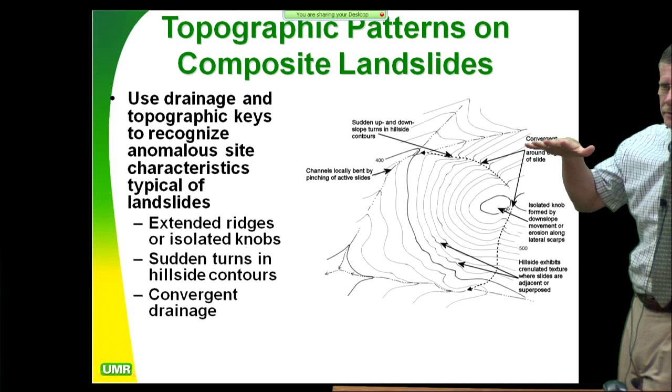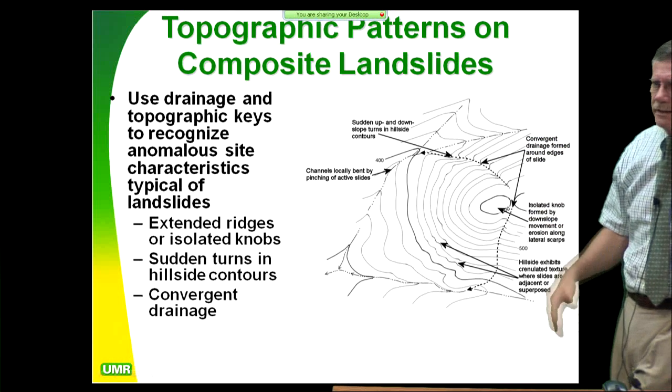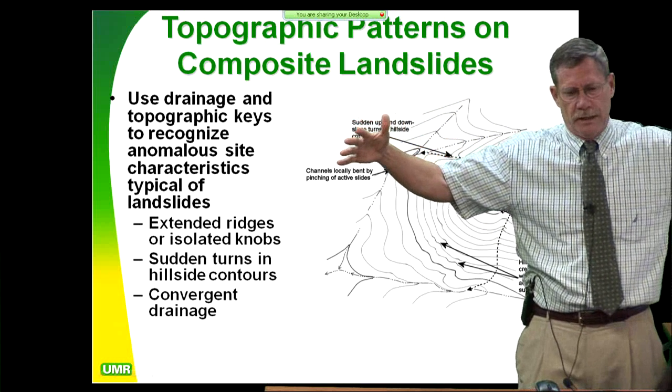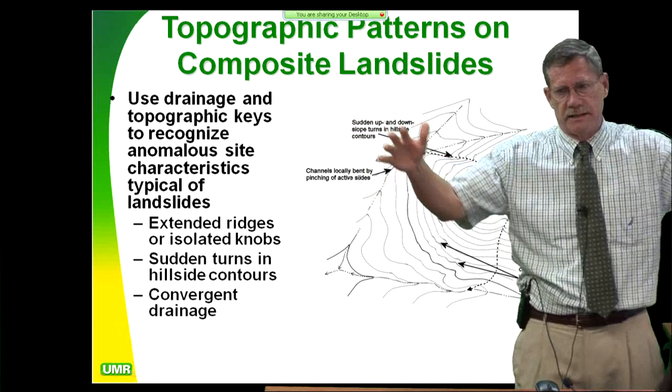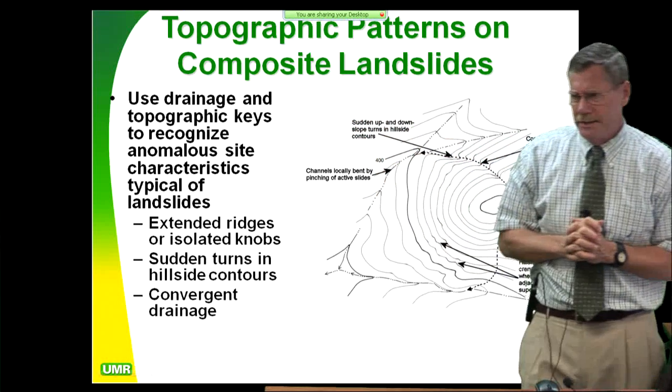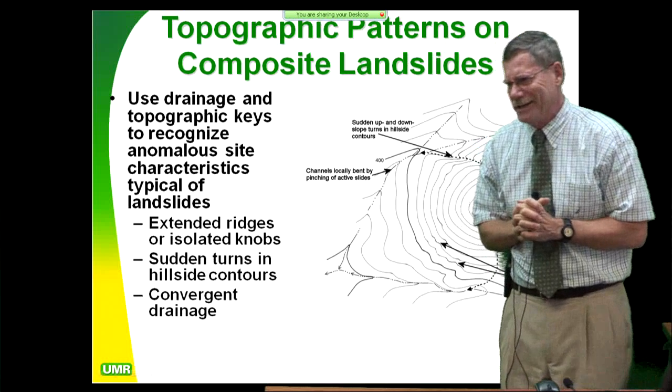So the lake started dropping down, and all of a sudden they started having wholesale pieces of the land around the lake start sliding slowly into the lake. It was due to rapid drawdown. And they said, "Well, geez, it's not rapid. We're not dropping it at a foot a day, we're going like an inch a day."